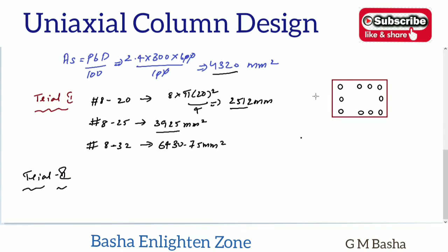And if I choose 12 bars, like this, it does not fit exactly according to the sizes, I am just showing a rough indication. All of it has to be provided with equal spacing, but going by the logic, 1 2 3 4, 1 2 3 4, 1 2 3 4, it is suited. Twelve bars will be okay for equal on all faces.